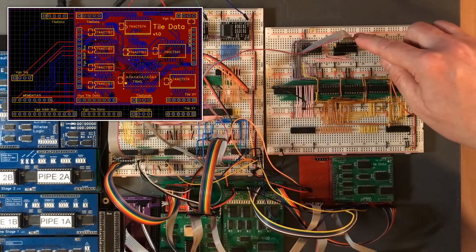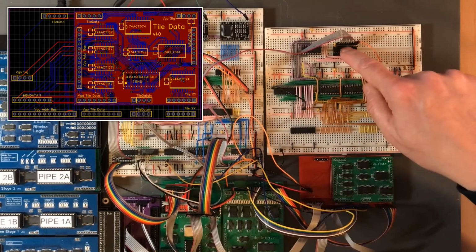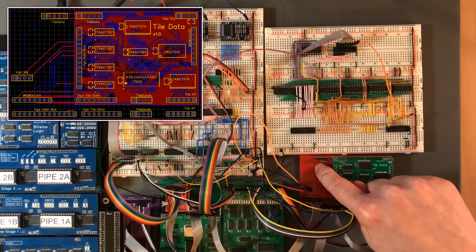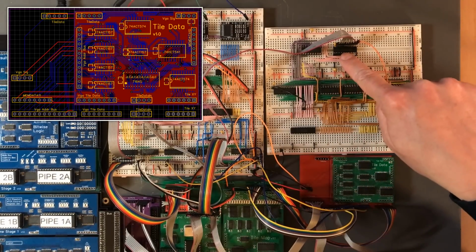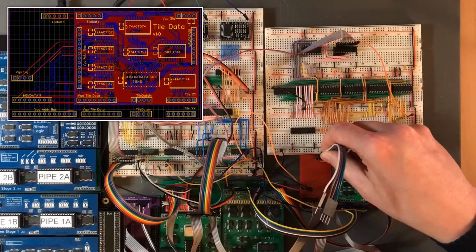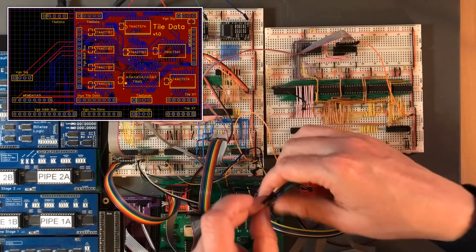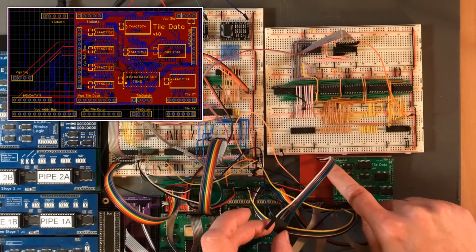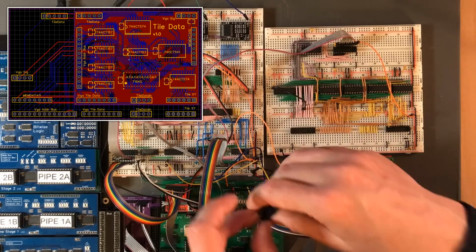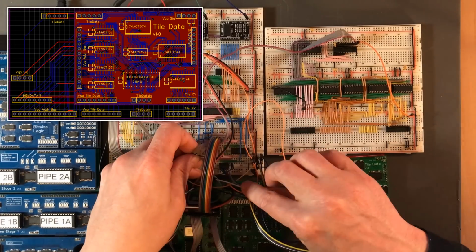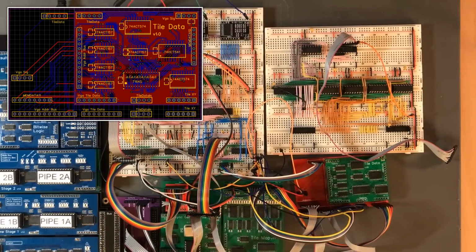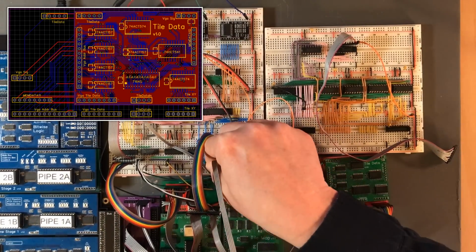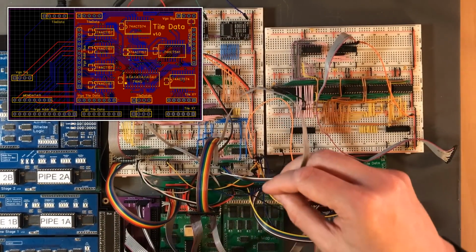Right, outputs are a bit trickier because we generate 8 output bits here, but we've only got 4 here because we just pulled the upper 4 bits low. That's interesting. We actually put the lines here the opposite way around that we'd want. So bit 0 is on the left. Just going to use this longer DuPont cable to tie those to ground.